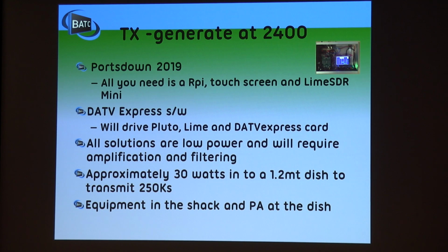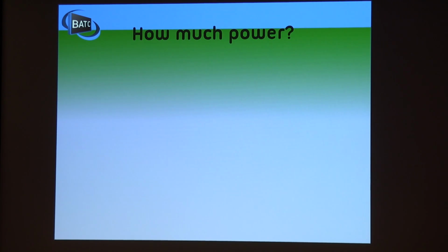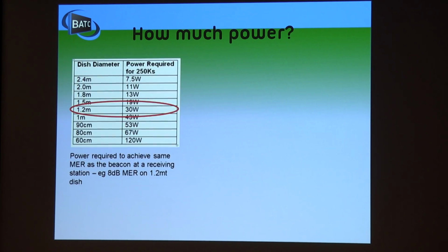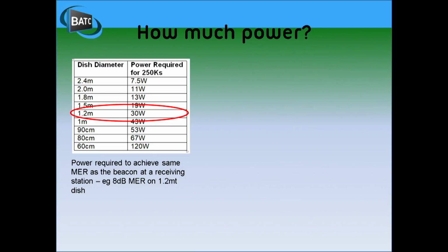So how much power do we really need? The numbers are more complicated for DATV because as the bandwidth changes, the amount of power you require is less or more. So what we've tried to do to give people an idea of how much power is to say, if you want to be at the same level as the beacon, if you remember in those spectrum monitors, if you want to try and deliver the same MER or signal to noise as the beacon does,